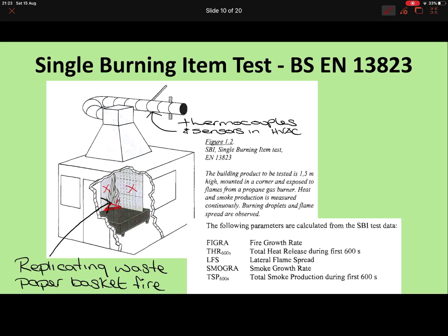It's calculated by optical detectors, and how much light is prevented from getting to the sensors. I was under the impression it actually calculated the smoke volume, but it doesn't. It's a little less technical than that. I'm sure it comes to the same results, but that's basically how it's done. It's done via how much light is prevented from getting to the emitter, and the only thing that can do that is the smoke particles, because that's the only foreign product that exists where the sensors are.